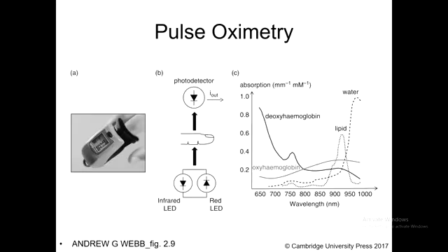One thing I forgot to mention this morning, I should come back to that. I did mention to you that LEDs don't like to get too hot, correct? And they fail under heat stress. Another thing they don't like is being reverse biased.